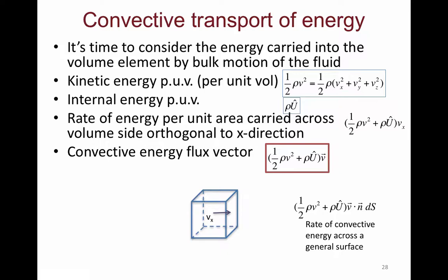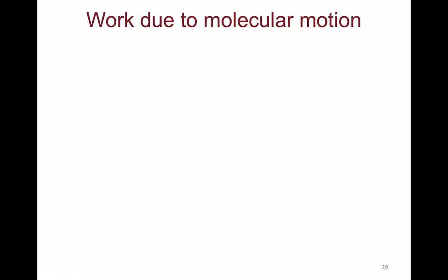Okay, so, and then of course, because of that, that's why we say that what goes out through the other side goes out if it's going in the same direction. So, more general formula is simply V dot N. So this is the projection on the normal. Okay, so only things normal to the surface actually enter. All of the tangential components simply slide and never enter the medium, so never change anything inside of that control volume. And dS is my area. So if I were collecting things, I would go and integrate over that surface. Cool. So that is the energy flux vector.